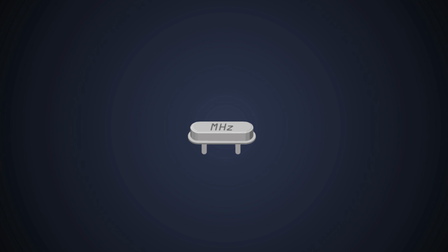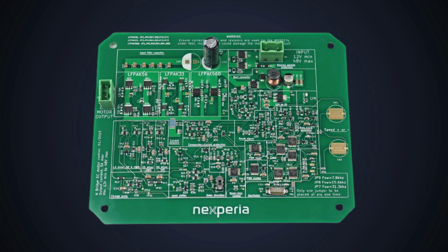Let's say I have to use this crystal oscillator and generate multiple frequencies out of it. I'll take a circuit where I don't want to use any type of microcontroller for now. For example, I have this board. In this, we are using multiple frequencies such as 62.5 kHz, 31.3 kHz, 15.6 kHz, etc., which are required for this circuit, such as PWM, clock, or charge pump circuit, which we saw in the last video. We'll use the counter for this circuit.